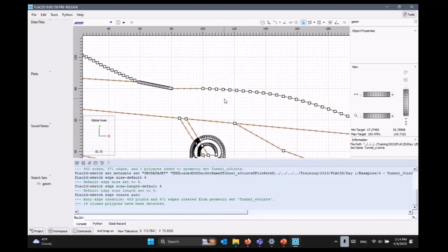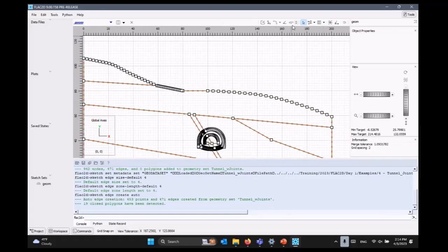Let me start first with this big part. For that, I can select all these connected edges at once by clicking on this button, selecting by break angle, and I'm going to set a slightly smaller break angle for the future. Any value like 25 degrees is fine. And if I click here, it will select all these edges for me.